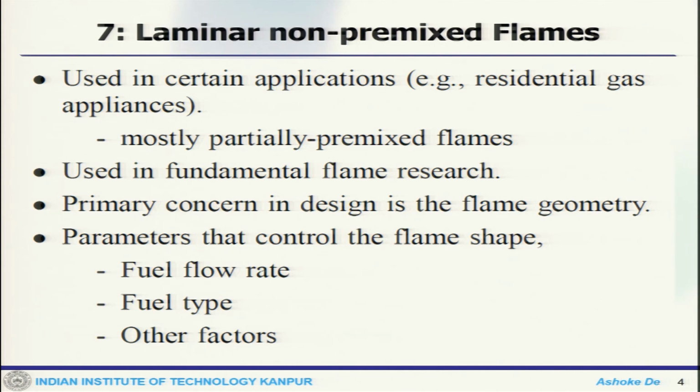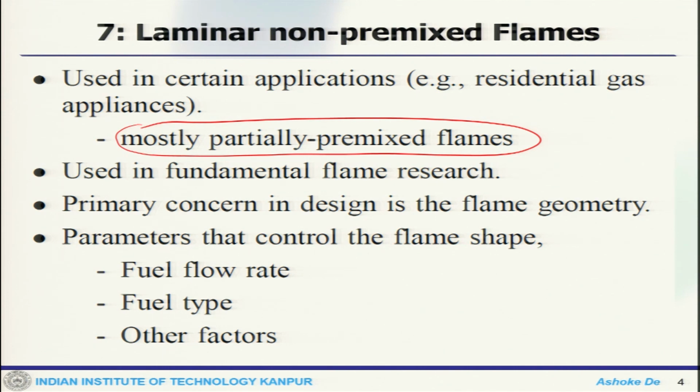Now, application-wise, obviously the applications of the non-premix flame are many, starting from your residential gas application, though that is a slightly partially premix flame. You can have it in plenty of places where it is used, and we have already seen that. It can be used in fundamental research. One of the concerns is how you can control the flame shape. You can control it through fuel flow rate, through fuel type, and also through other factors.